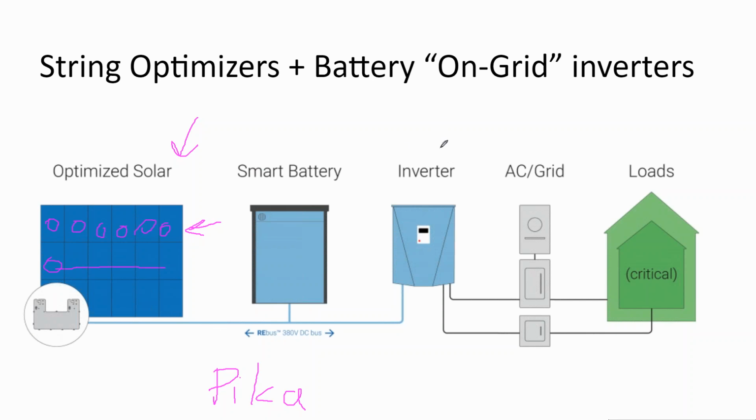And what that means is your inverter costs can go down a little bit, because instead of being fed a variable voltage that spikes up and down, the inverter is being fed a constant voltage with variable amperage. And it's a little bit cheaper to control your equipment costs with a constant voltage rather than a spiky voltage. And so they're regulating the output of this home run circuit and keeping it at a steady 380 volts.